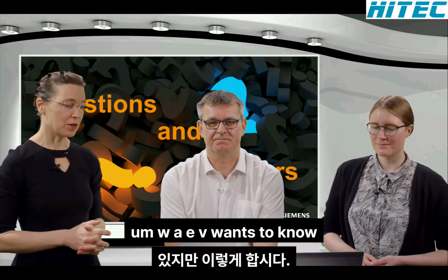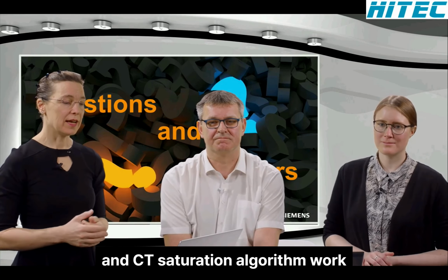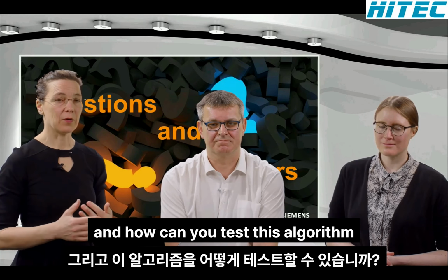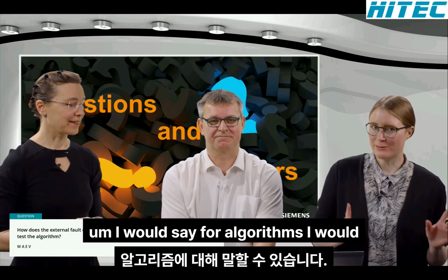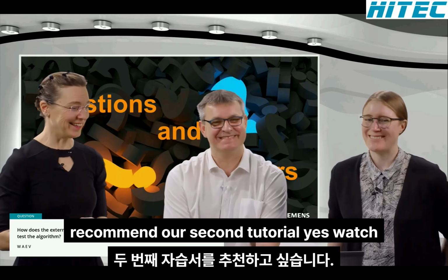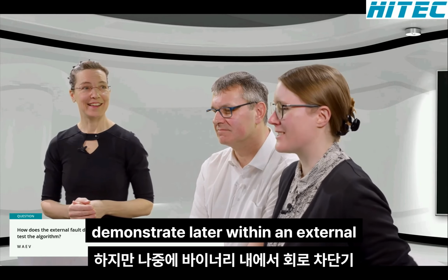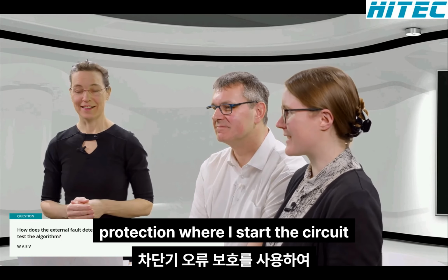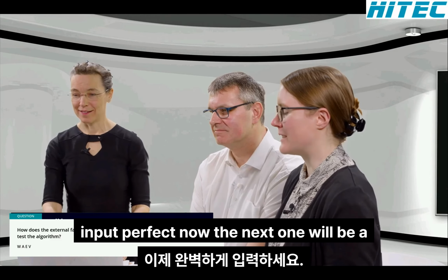WAEV wants to know, how does the external fault detection and CT saturation algorithm work? And how can you test this algorithm? I would recommend our second tutorial for algorithms, so watch the recording. But I want to demonstrate later with the digital twin an external fault with the circuit breaker failure protection, where I start the circuit breaker failure protection with a binary input.